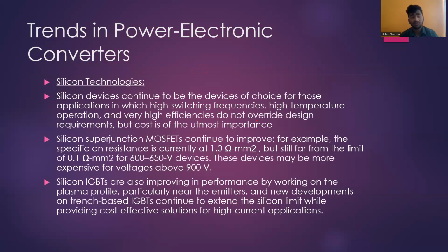Let us discuss the other trend in power electronics: the silicon technologies. Silicon devices continue to be the devices of choice for those applications in which high switching frequencies, high temperature operation, and very high efficiencies do not override the requirements, but cost is of utmost importance.